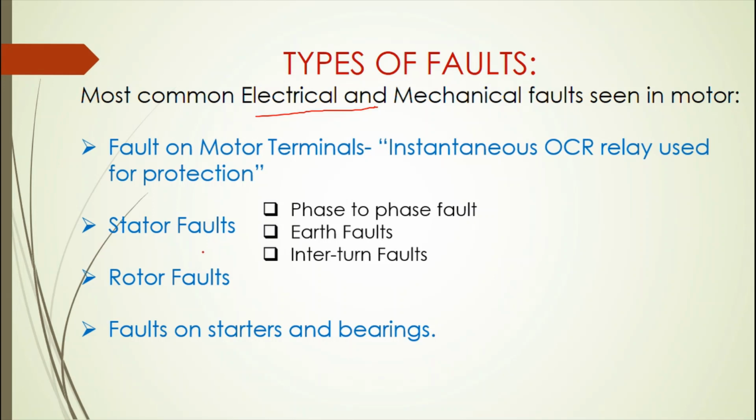Stator fault. Faults in the stator or motor winding due to any insulation failure or insulation breakdown are generally termed stator faults. The faults occurring in the stator can be phase-to-phase fault, earth fault, or there can be a possibility of interturn fault. Although the probability of earth fault occurring is larger, phase-to-phase fault occurs very rarely.